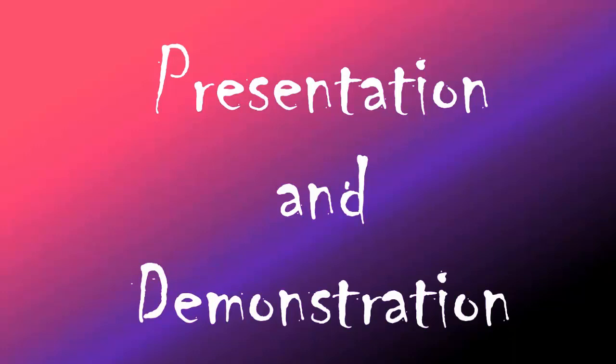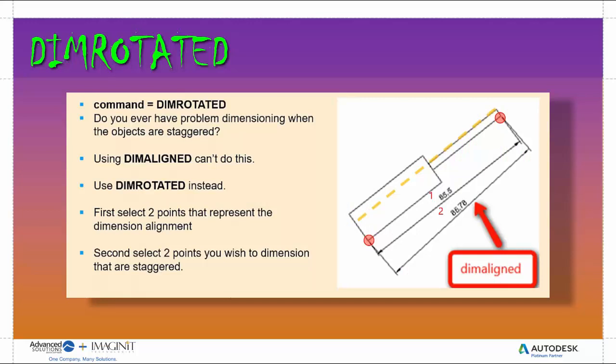And without further ado, we'll go ahead and jump into the presentation and demonstration portion. The first thing we're going to talk about is the Dim Rotated tool, along with all of the other dimensioning options you have available, such as Dim Aligned. Dim Rotated is a slightly different version where it allows you to dimension an item along an angular degree where the elements of your line may not meet directly, but you want the extension line to come right off of that point. I'll switch to AutoCAD here and demonstrate.